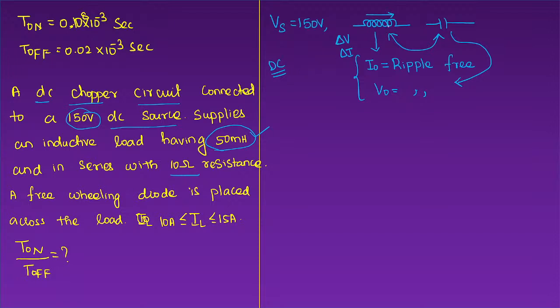Conclusion: we are talking about DC voltages. So on the output side, though the inductor is present, during the calculation you need not consider it. When you are calculating the output voltage and output current, it simply behaves as a short circuit. So it is not mandatory to evaluate the properties of the inductor directly. But you can use this inductor to know the output current. Basically, this inductor is only dealing with the output current. The capacitor deals with the output voltage. If the capacitor voltage is given, that will be equal to the output voltage.